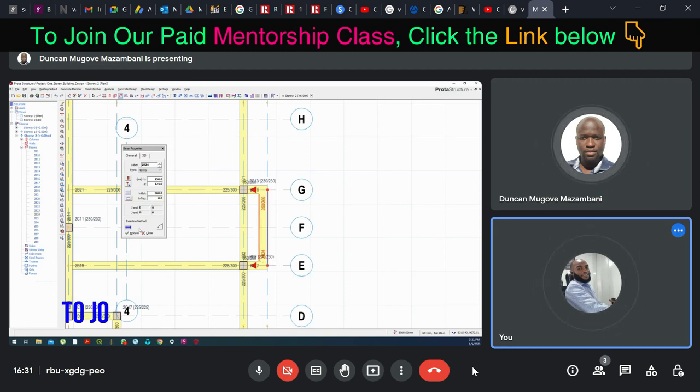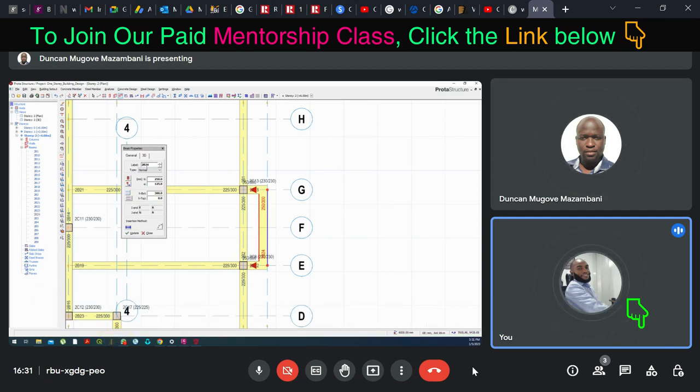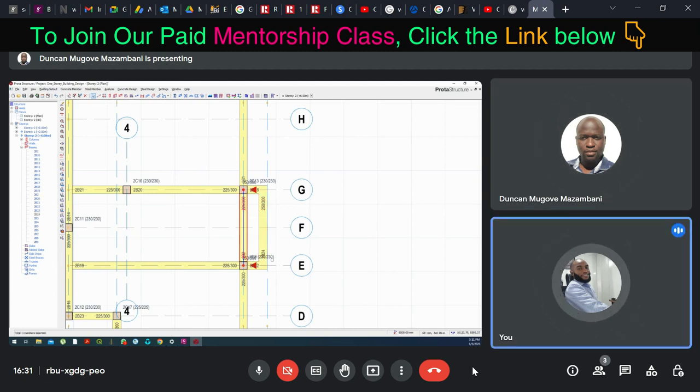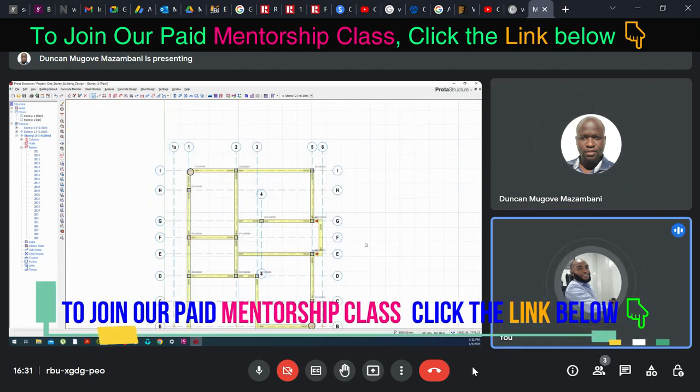That's fine now. Okay, now delete this beam inside. Click escape first, escape or close. Then delete that beam inside, because we have now made a new model. Take off the beam. That's fine. Now do the same thing for the other side of the cantilever.